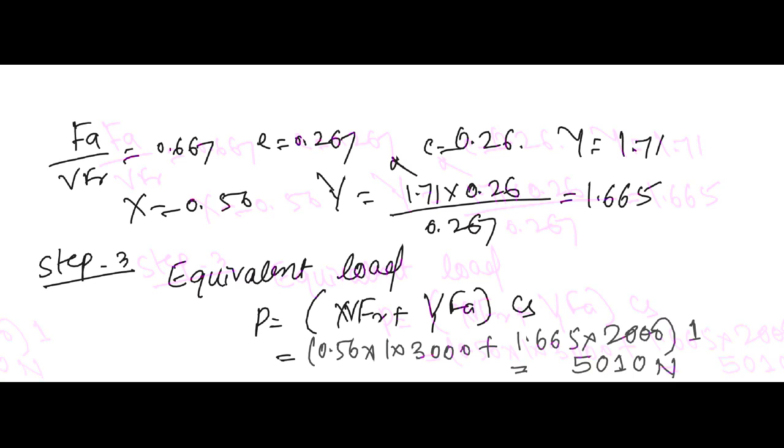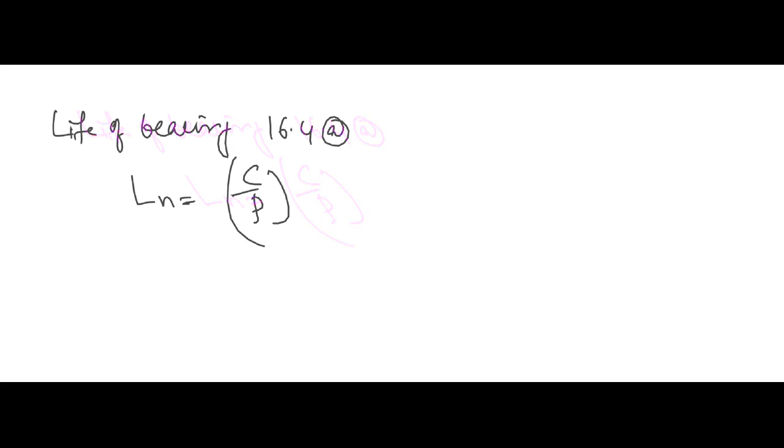Okay. Now we calculate the life of the bearing. Refer equation number 16.4a. Now Ln equal to C by P to the power of 3. So the value of C is 47,000.